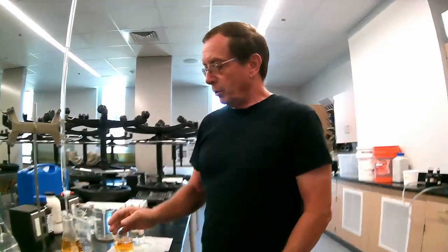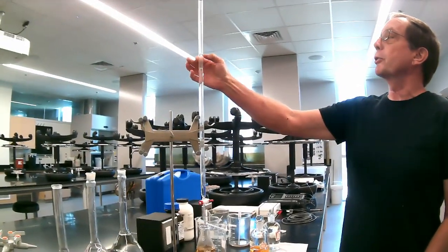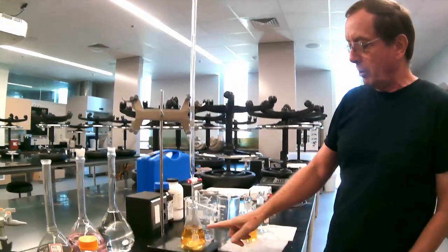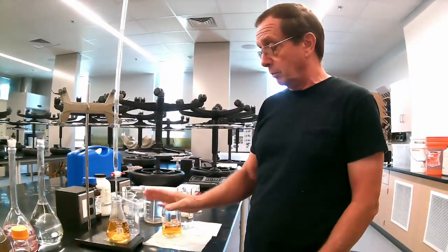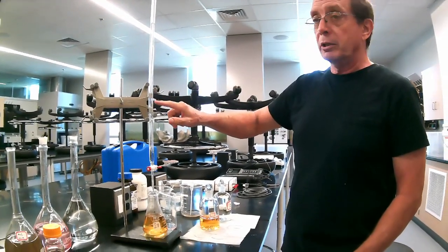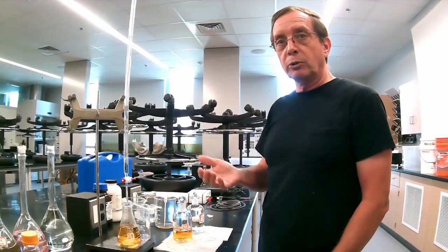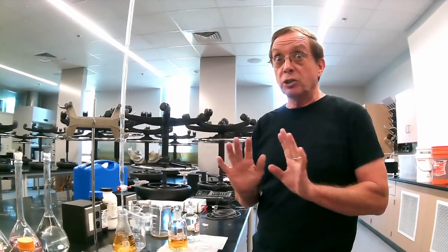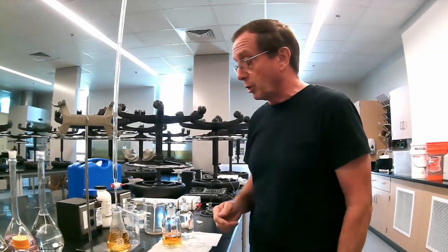Okay, so here's our sample, 200 mils. This is our titrant. We're starting at 13 on the burette, and we're going to lower that down until we clear this sample. When it goes clear, then we know we're done. And the difference between where we started and where we ended is directly proportional to the oxygen concentration in milligrams per liter, right? So our milliliters, we've set the chemistry up that way so that it's easy, right? You just take that subtraction, that's your oxygen content.